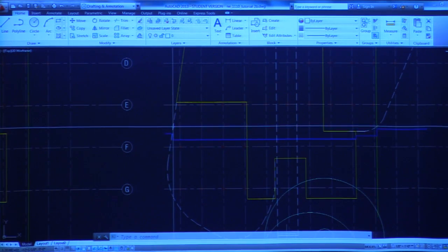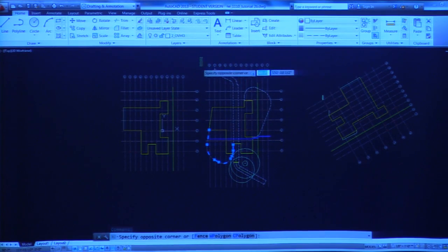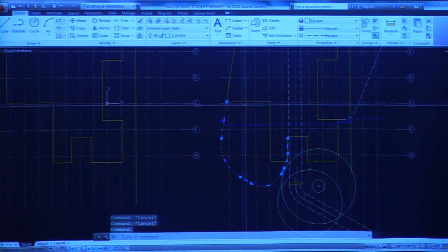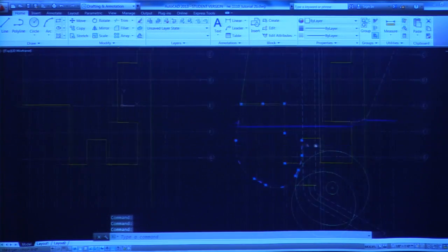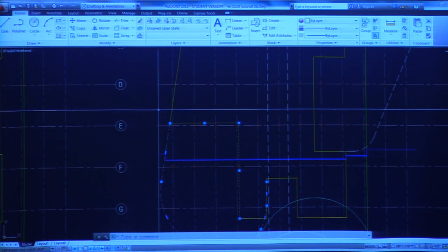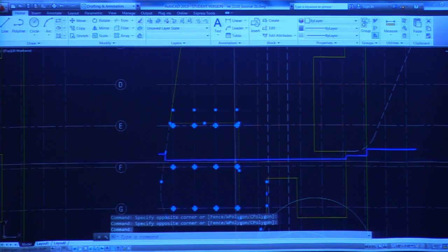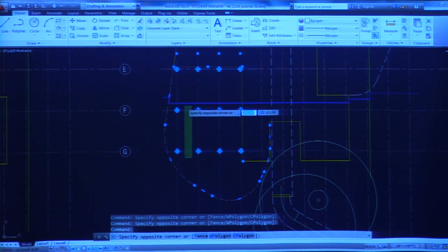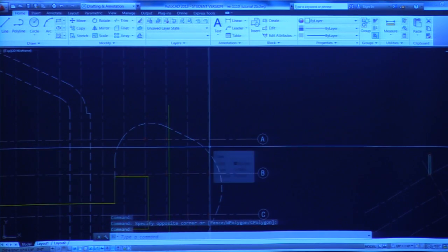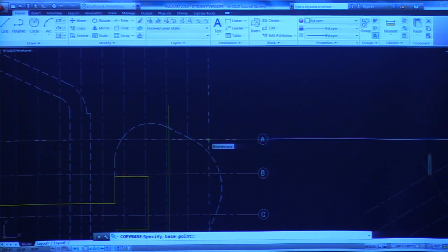And I'm going to grab some elements that I had used previously to help move this along. Those elements are going to be this overhead lobe, this wall, and here's a handy little thing. I'll grab these columns for the heck of it, these grid lines again, and these grid lines. But I'm going to do that copy thing again. So I'm going to press Control-Shift-C all at once, or I think on Macs it would be Apple-Shift-C.